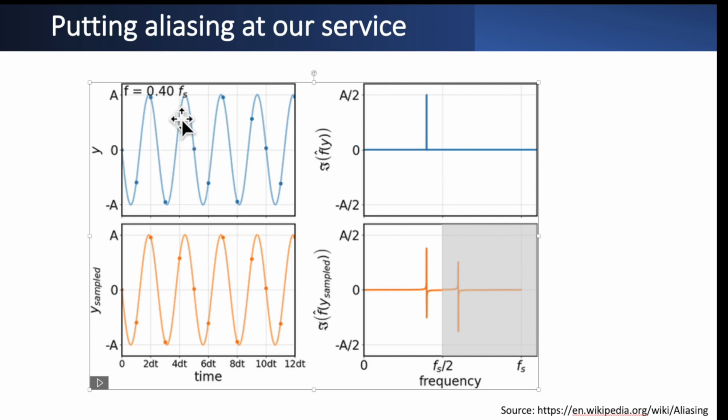We see here in blue the blue dots are the sampling points. This is the ideal frequency domain representation that we would get. And down here in orange we see again the sample dots and the reconstructed waveform by FFT, and the frequency domain as we would see it from the FFT analysis. At this particular frequency everything is still looking perfectly well, because if we take these sampled values, we can exactly reconstruct the signal that we're looking at. I'm also assuming here that the oscilloscope or the spectrum analyzer with FFT or the computer is showing the reconstructed frequency spectrum up to half the sampling frequency, also called the Nyquist frequency, because that is the maximum signal that you're supposed to be allowed to sample given a sample frequency of Fs.